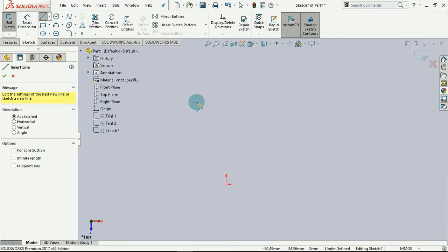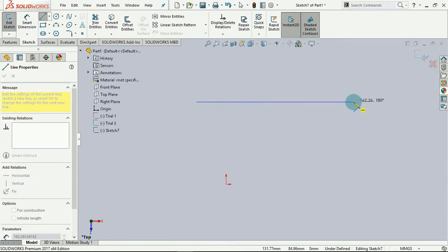We're already accustomed to this, which is just a straight line. And also I would like to give us this hint. If you notice while I'm drawing this, there's a yellow icon showing close to my screen. If I move upward, it disappears. When I bring it downward, it appears again. So that works like a snap that helps to detect if your line is horizontal or not. So taking it up surely means it's not horizontal, but bringing it down, you notice the degree is 180 degrees. If I come this way also, it gives an icon that represents vertical, and the degree there is 90 degrees. So that also helps us to draw vertical and horizontal lines.